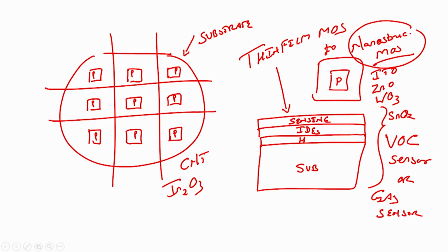The nanostructure would show a higher sensitivity at a lower, room temperature because it has a higher surface to volume ratio compared to thin films, and that is why we go for a sensing layer which is made up of nanostructure materials. So, we will see in this lab how the carbon nanotube looks on the wafer which has those sensing layer. So, CNT is a sensing layer on the wafer which has the interdigitated electrodes, alright.